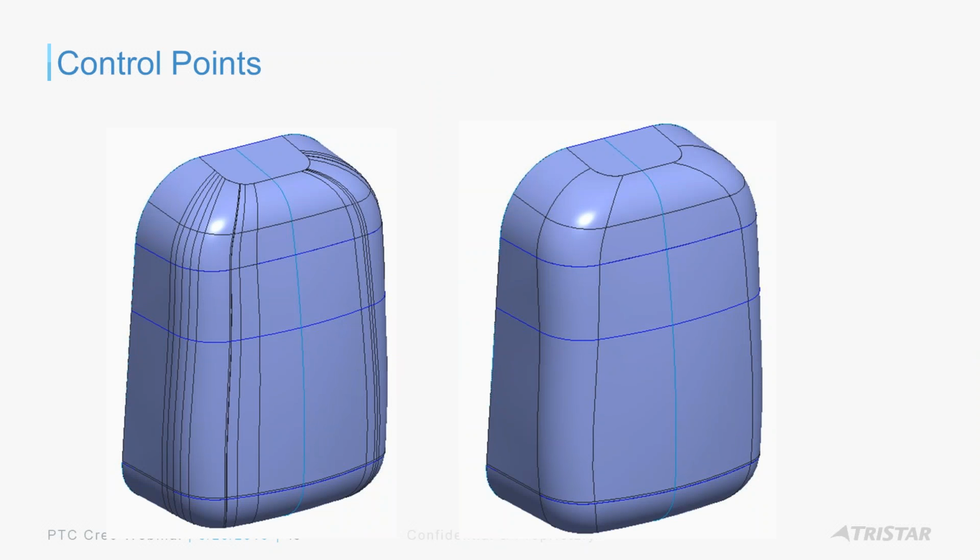If you were to use technical surfacing, when you add your boundary blend curves in first direction and second direction, like in this model, you could see how by default what I'm getting is quite a few patches. Now that might create an issue when I try to thicken the surface and solidify it, right? That's not a clean surface. How do I get rid of that?